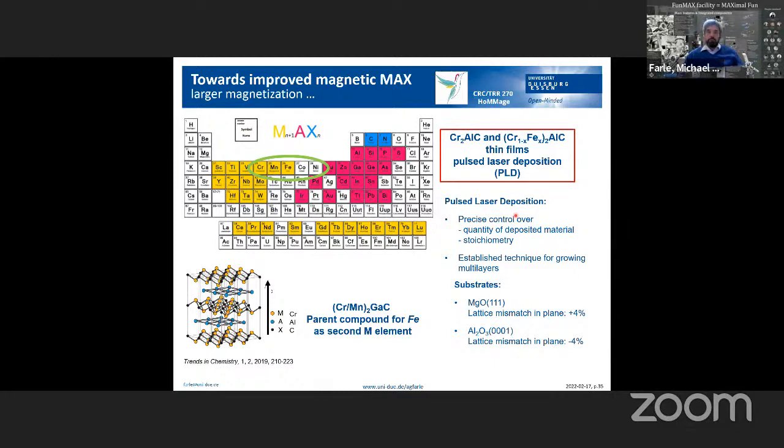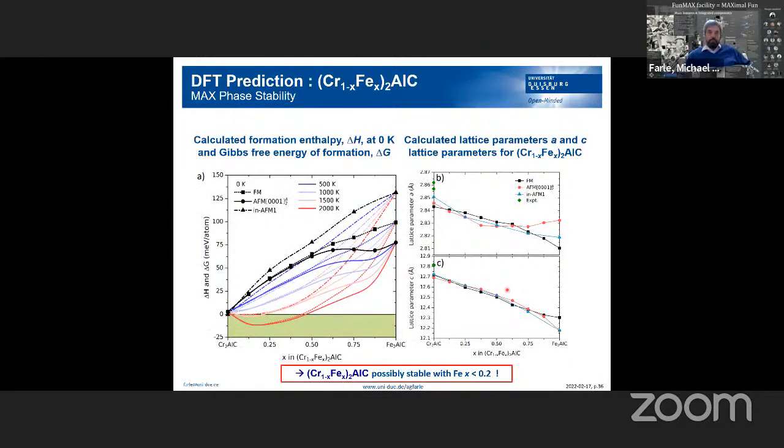With sputter deposition, so far it didn't work, also not in other groups. One has to take care of the lattice mismatch. Since we have hexagonal structures growing, one usually starts with the 1-1-1 type of orientation at the interface. Okay, now the theory.